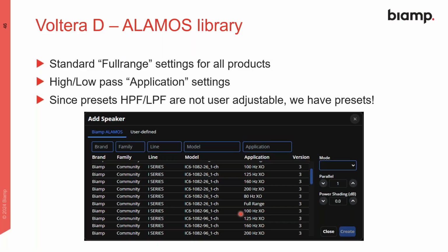between them. If the subwoofer's in close proximity to the full range, this could help us later on in the commissioning phase. We might not have to EQ out a big low frequency bump. If we selected 100 hertz high pass, 100 hertz low pass, and you do the typical thing where subwoofers may be gained up 4 to 6 dB higher than the full ranges, well, you're going to have a buildup.